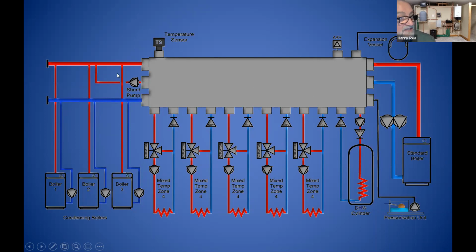But now these boilers can actually be doing the vast amount of work. And if there's really, really cold weather for a week in the year, the old boiler fires. So instead of spending a fortune building a boiler that'll only be pushed to its limit for a few weeks in the year, you let your superbly efficient boilers do 99% of the work. And yes, you rely on the old boiler, but you've just saved the owners of the building a fortune by not having to waste money putting in a boiler they're not really going to use. So you can combine the old non-condensing boiler with the new condensing boilers, and both of them will work away perfectly happy.